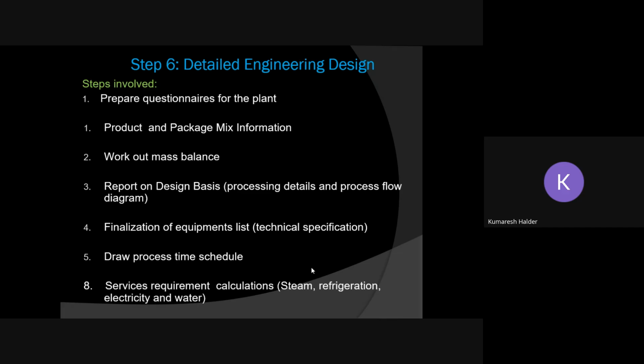They can do this work. That is detailed process engineering, or you can say this is the base or heart of the dairy plant design. And for any kind of dairy business you want to start, this is the heart of the DPR. So you need to prepare questionnaires first for detailed engineering. Detailed questionnaires mean: what is the capacity of the dairy plant, what kind of milk you are going to receive, cow milk, buffalo milk.